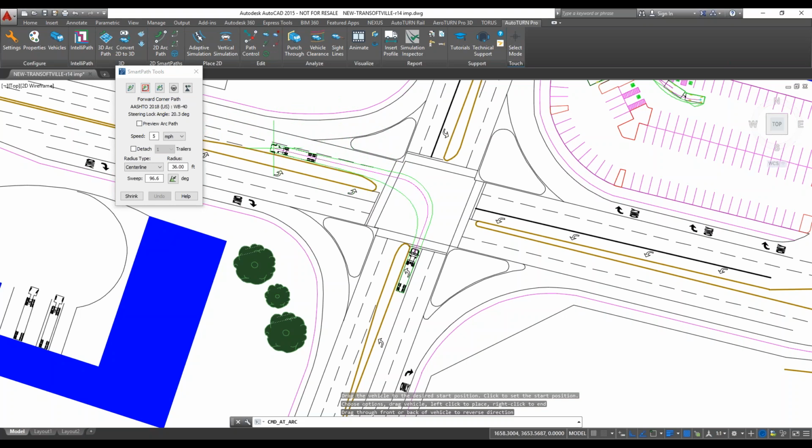because it'll let me generate the maneuver. And you can see right now, because I was using it before, it already has the sweep angle for this intersection, which is not 90 degrees, it's slightly over 90, 96.6. We can use geometry or indicate or tell the software to calculate the sweep angle, this is my reference geometry. So it's actually 95.9. It wasn't 95.6 as we saw before. And now my vehicle is aligned with that geometry.